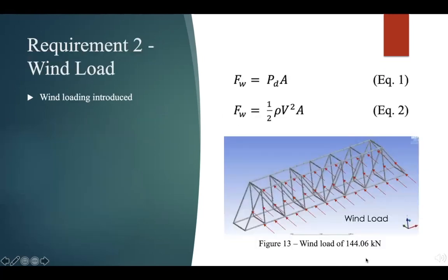After understanding the deflection and stress developed by crowd load, wind loading was introduced to complete the design requirements. The wind speed was first converted to dynamic energy, transforming to pressure applied at the wet surface of the bridge. The pressure was then converted to the applied force just to simplify the loading calculations shown in equation 2. It was assumed that the wind force is applied perpendicular to the walls of the bridge, uniformly with a smooth interaction as shown in figure 13.